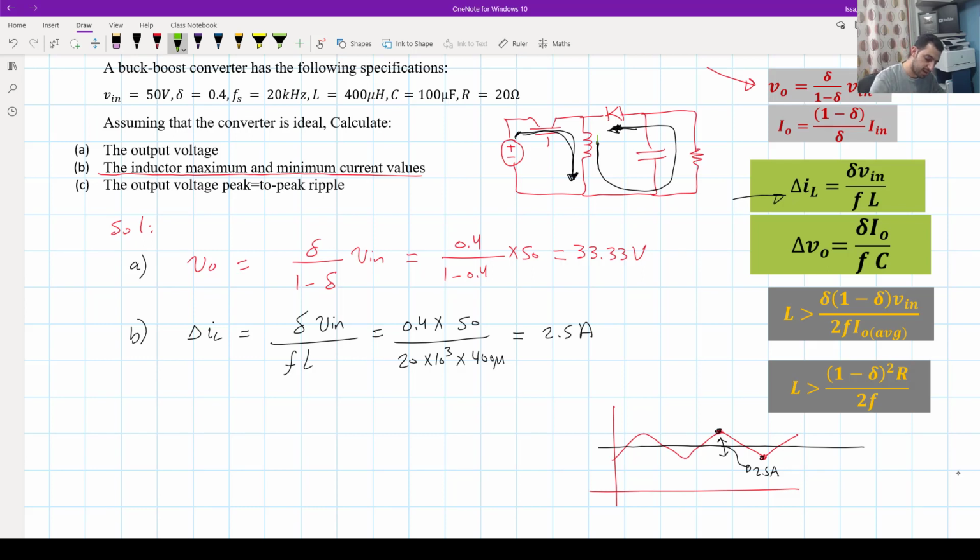We can say always that the inductor average current will go now like this in the off time, and the ripple will go through that capacitor, but the DC component will go through the output resistive load. So I think the average or DC component of my inductor current is the same as my output current, but during the off time. So these are some other solutions and suggestions. If I calculate my output current during the off time, I can really know the inductor average current, and I can use it to calculate that level here.